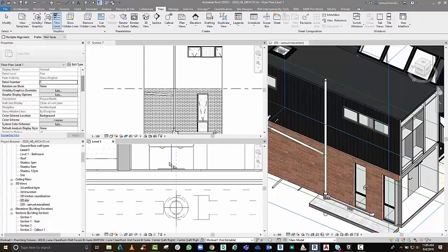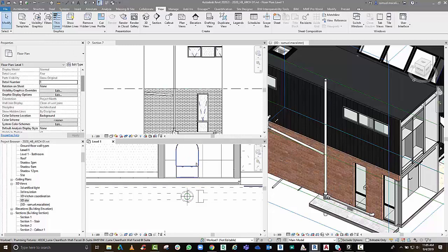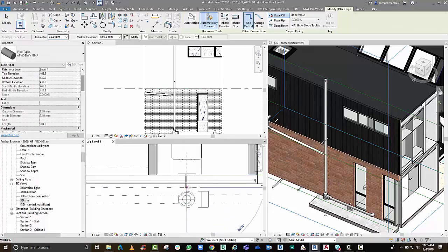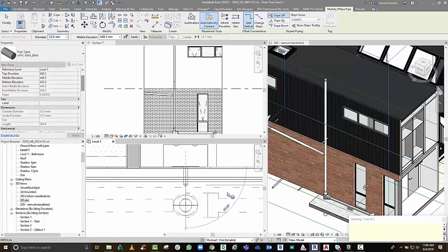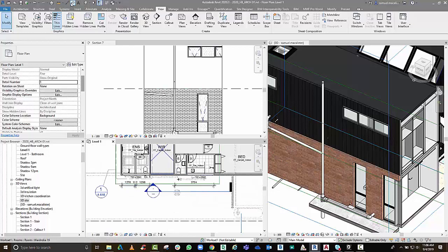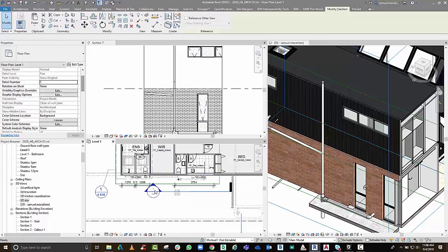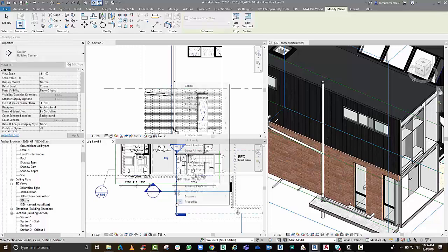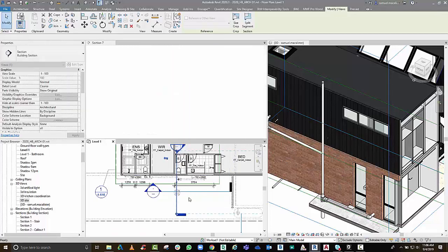And what I want to do now is actually connect it up with the drainage pipes we have here. So what's really cool is Caroma have built this with intelligent supply pipes and outlet pipes for me to connect up inside of Revit. So to do this, I'm just going to flick to a section view here.